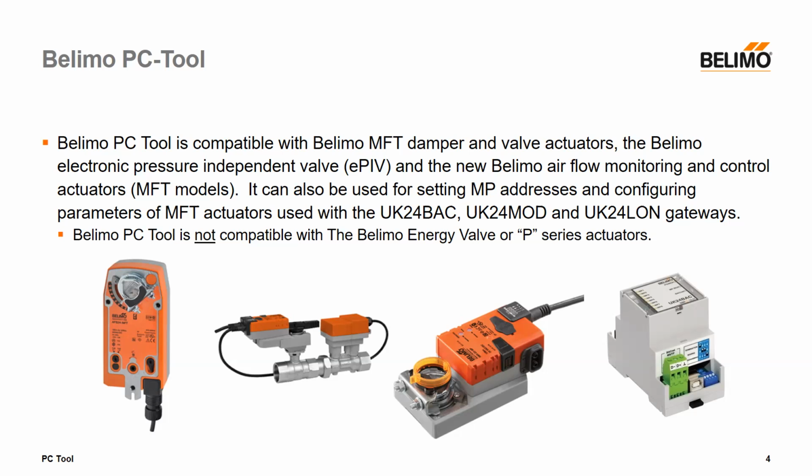To make it more confusing, just so you all know, if you connect to a P series actuator, you can actually view it with PC Tool. Where the problem comes up is that you're unable to write to it. So the P series actuators that you'll see on our, say, 8, 10, and 12-inch butterfly valves, or possibly in a standalone airside application, are really not compatible with PC Tool. And the Belimo energy valve also is not compatible with PC Tool.